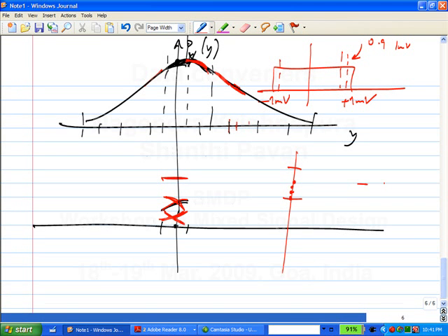You can simulate it also and see very easily. You put in even a sine wave and you find the distribution of the quantization error, it will look more or less uniform. Okay. The only time it will not be uniform is if you divide it up into only 2 steps. Okay, then it will become very crude. But as long as you have a reasonable number of steps, it doesn't have to be very large also. This is a very good assumption. Okay. Is that okay? Okay.